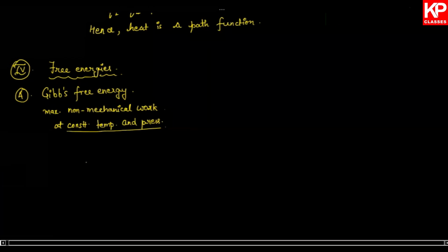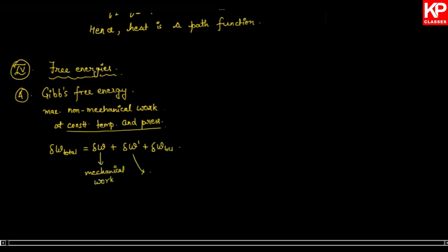All right, now we will see how this Gibbs free energy is related to the non-mechanical work. Before that, we have already seen that the total work done is basically the mechanical work plus the non-mechanical work plus the loss. This here represents the mechanical work. ΔW dash is what I am using to represent the non-mechanical work.